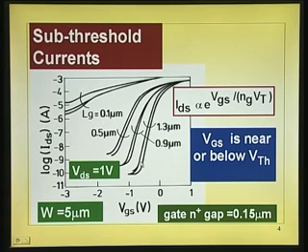Now, first, before we understand why it is not steeply falling as we reduce the channel length or gate length, what we have to understand is how it will fall when the long channel device is present. Okay. I will keep this curve, we will go through the analysis, then we can understand this. So, these devices were for channel width equal to 5 micron and spacing between the N plus and the gate layer is 0.15 micron. Okay. So, these devices were for this type of device.